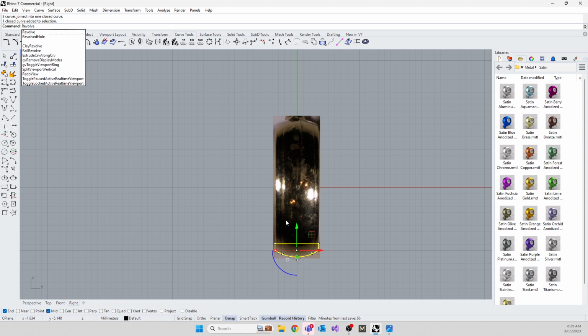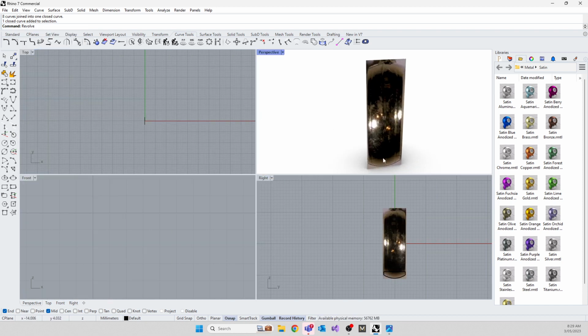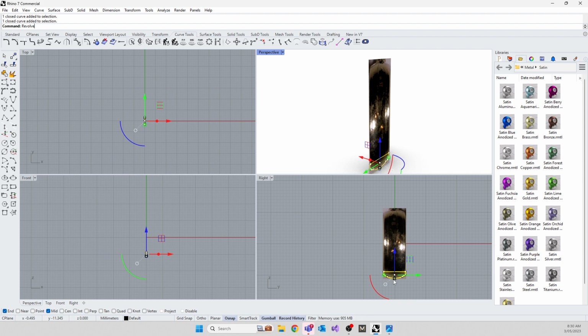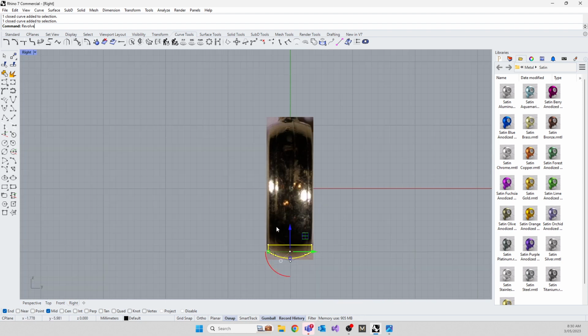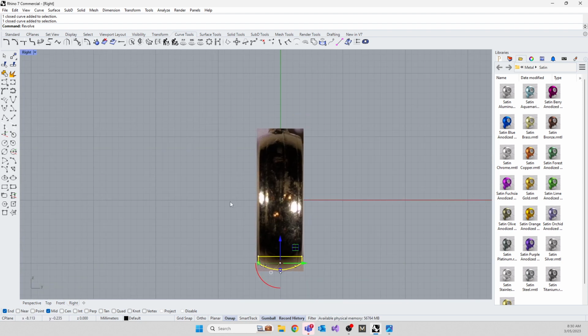We'll do this again very quickly. Revolve. Before I run the command, we want to draw this thing going around like that. We want to make a surface out of this thing revolving around the middle of the world in a full circle and coming back to itself. The command's easier to understand when I just do it. So I'm going to be in this viewport because we want to revolve in this axis. I'll type the word revolve.